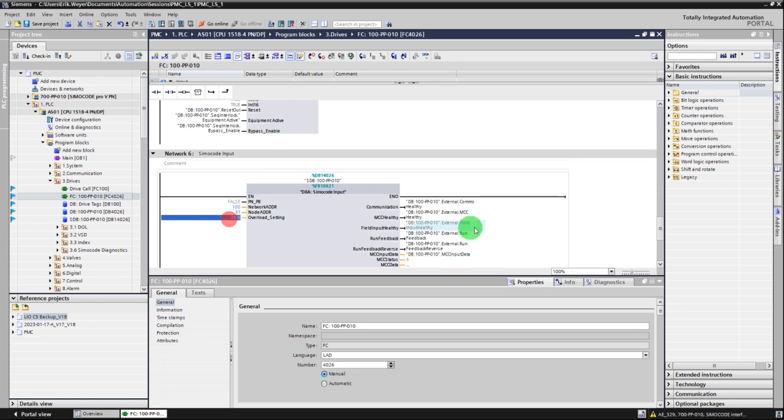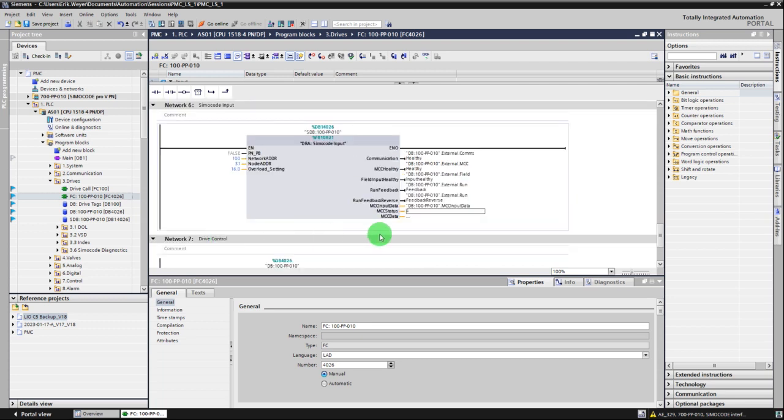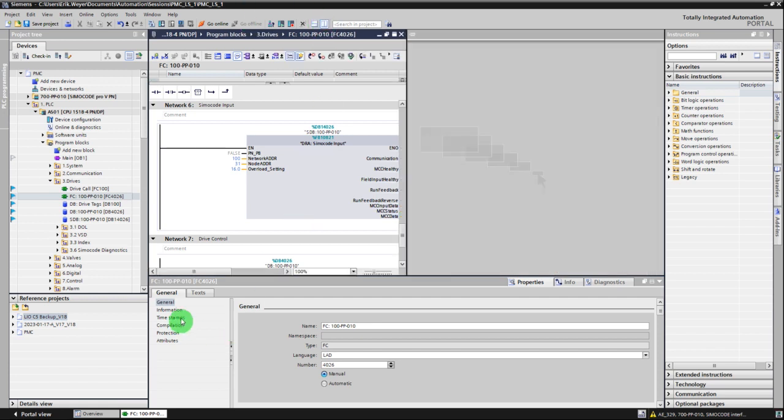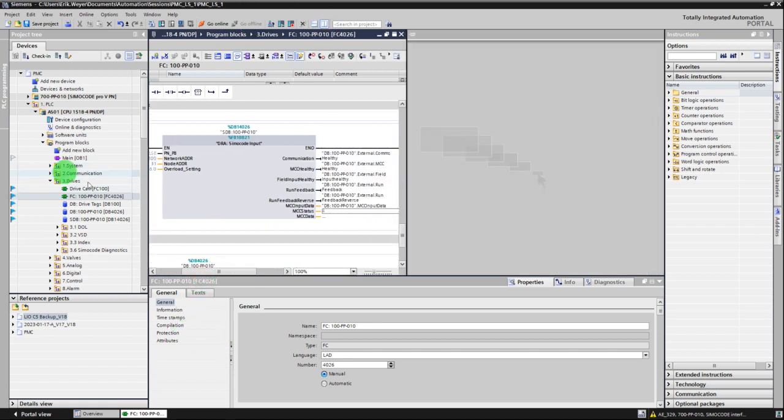Then the overload setting, this is just as a reference for SCADA purposes. So we have a 2.4 to 20, so just for argument, let's make it 16. Then afterwards, we've got MCC status and data. So this we will need to actually add from our UDT.